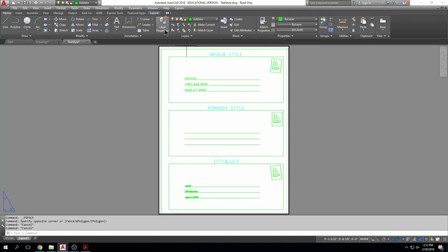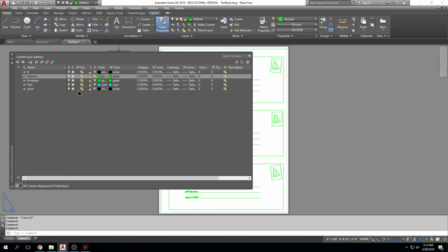How do we make sure the viewport doesn't print again? You're going to go to the layer properties and make sure that printer is slashed right there. Oops. Hit escape. Okay, so what's happening here? You're just trying to make this the exact same size as your page. That makes sense? You're almost there. Here we go. Okay, you grab that now. Ah, there's the problem, I think.